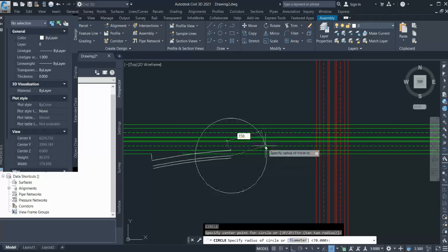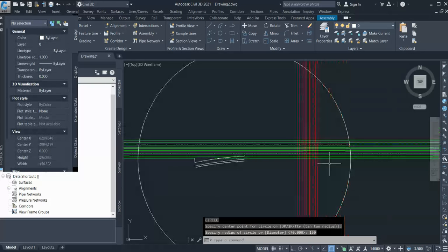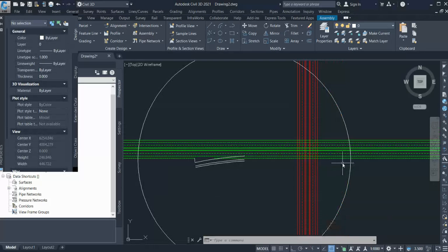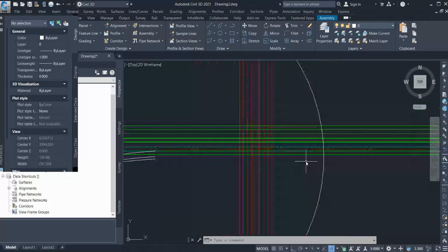Here now you can provide different kinds of arrangement. You can go with the diverge taper. You can go with the auxiliary lane, or in many cases, what people are doing, they generally go with the 3-lane road on the bridge section, here, this diverging and merging sections. So you can provide a smooth bridge design. So either go with the diverging taper, auxiliary lane, or you can go with the three lane.